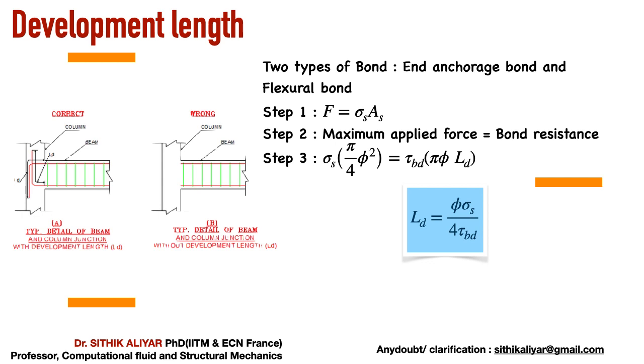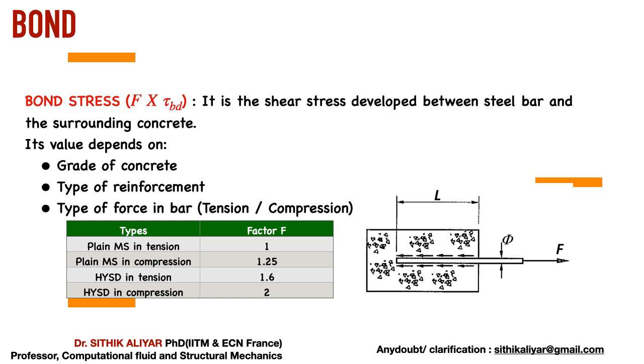From this figure, I am using the previous figure to derive the development length. You can see this one. Development length is nothing but how much length of the bar you should insert inside the concrete so that you will have a sufficient bond.